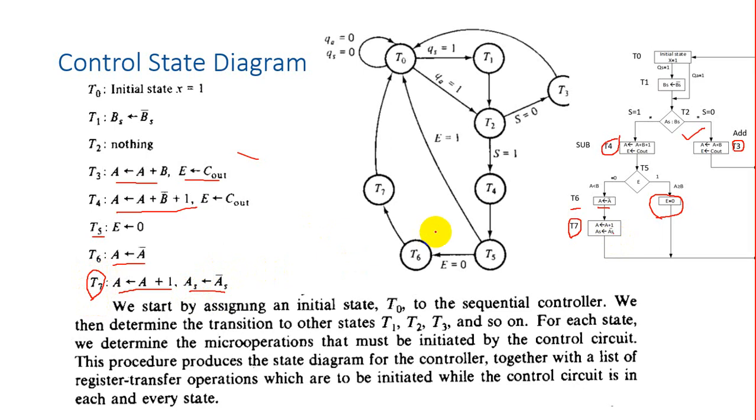Okay, on your question paper, usually they will ask you to write the control microprogram. Write the microprogram. So to write the microprogram, these are the steps. First, you need to find out what operations are happening at different T states. Then, to perform these operations at the different T states, what will the control want? Let's find out. Okay, so let's translate this operation to the control word.